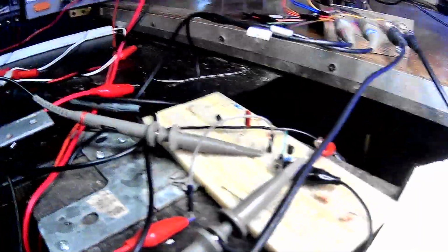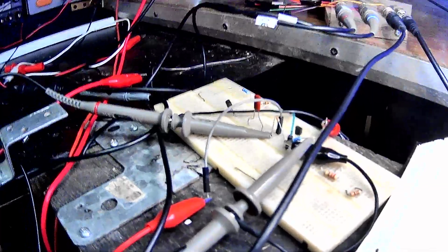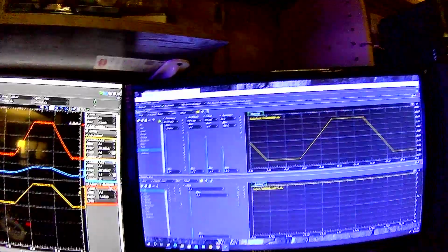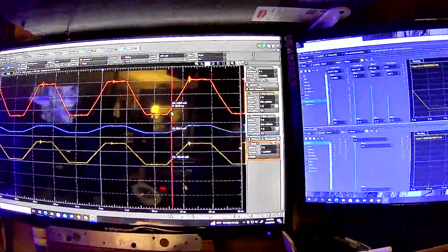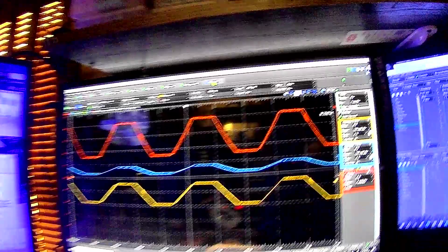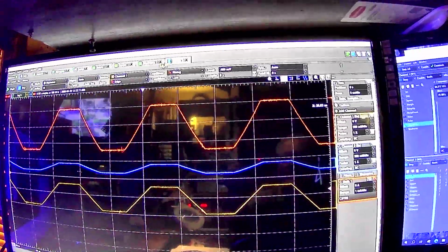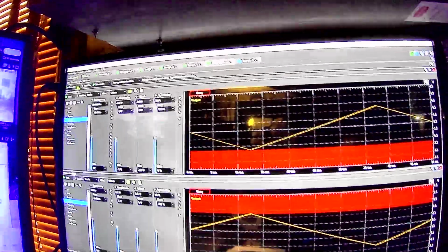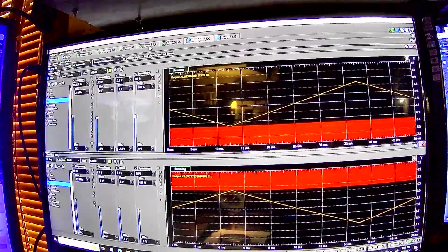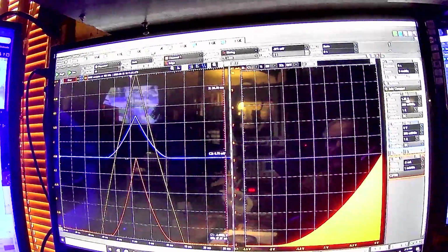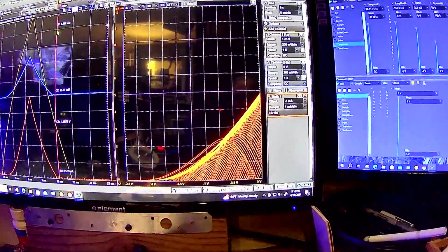Yeah, what's nice about this setup is that it's the same configuration where I was running the amplifier in the previous video, but it's actually pretty easy because I've got these different scopes. With this, I'm using it as an amplifier, but I can also very easily change over to looking at its transconductance curve, just by going to the right scope and hitting run all. And we don't want to run this because that's garbage. But go to this scope here and hit run, and guess what? Now we're back to seeing the transconductance curve.